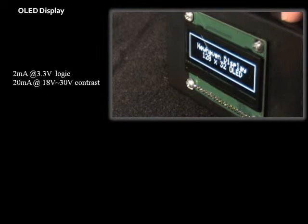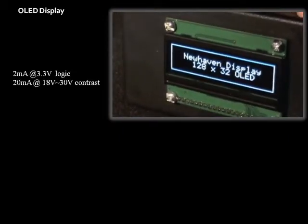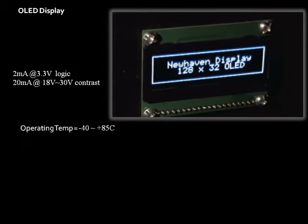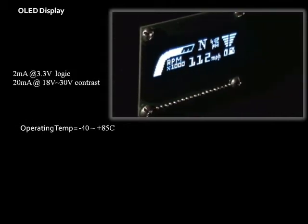OLED displays typically require around 2 milliamps at 3.3 volt for logic supply, but also require around 20 milliamps at 18 to 30 volt DC for contrast. Operating temperature for OLEDs is negative 40 C to plus 85 C.